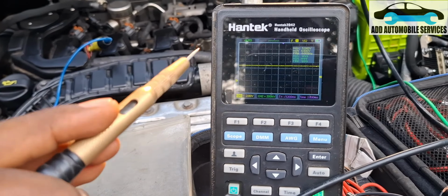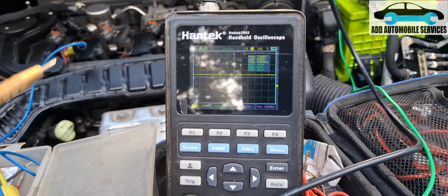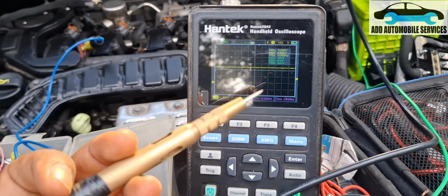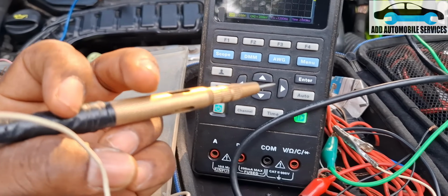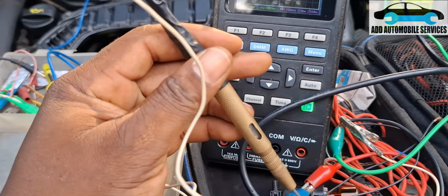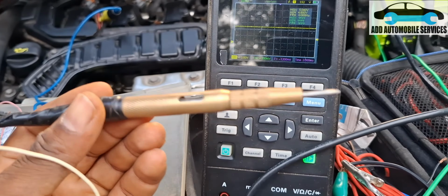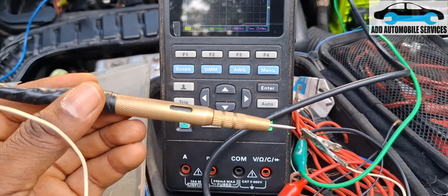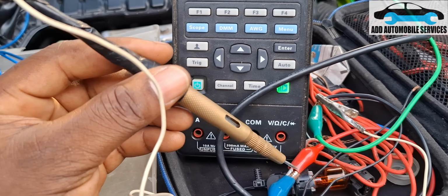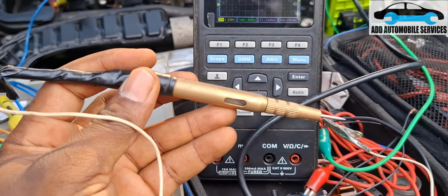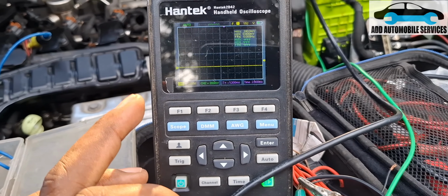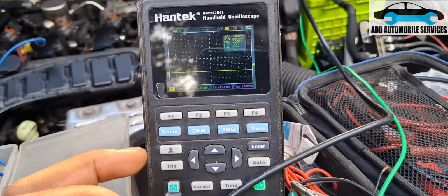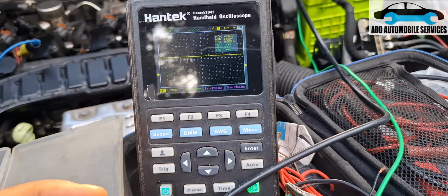Now I've got power and signal, and I'm searching for ground, so let me use this test light, because it also carries ground at the tip, so when it meets voltage, it will turn on. So if you can see, now it has come to ground. That means that's my ground line.